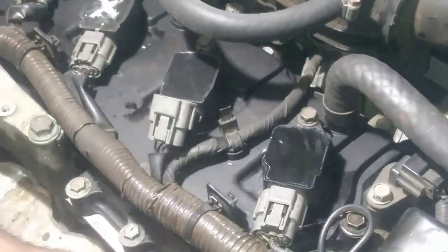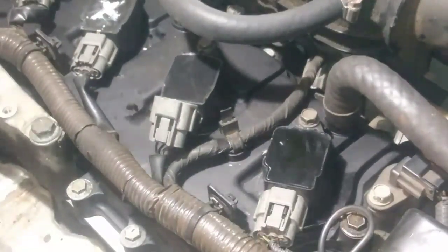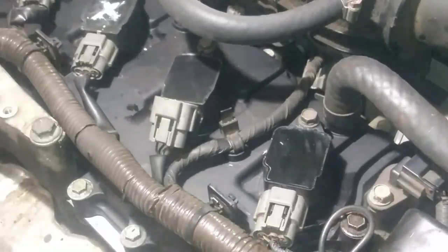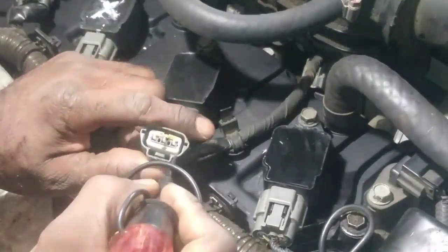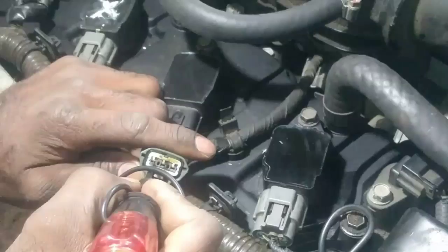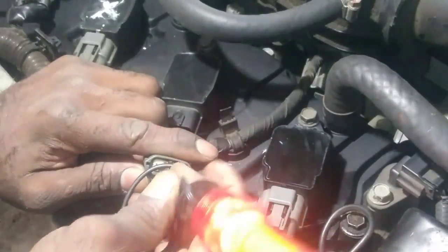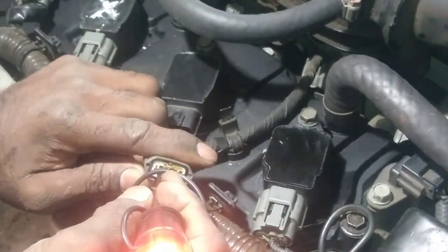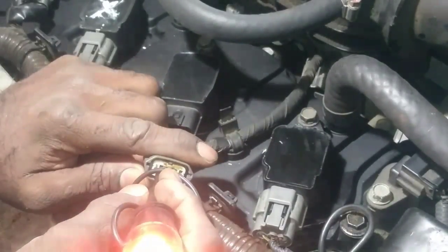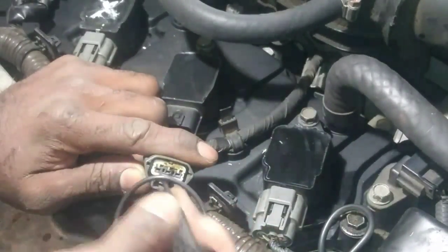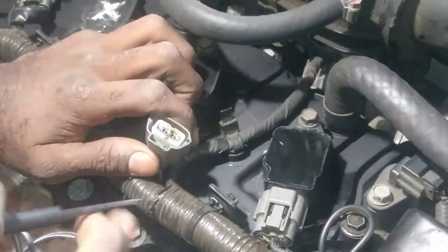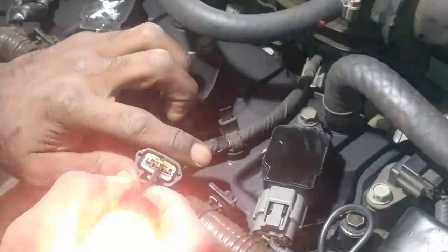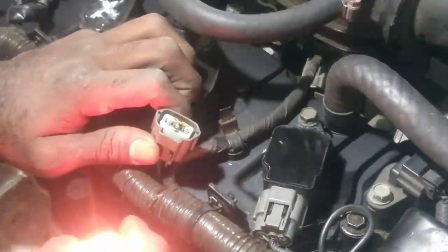We're going to check for ground, so we're going to swap this over to battery positive and check for a good ground. There's our ground here in the center. Let's check the other one. It's illuminating really faint. Again, the signaling side is going to be a low voltage reference, which is going to display that there's voltage there, but it's a resisting circuit because it's something switching inside the computer. I ain't make this stuff, but this is brighter, just like if I was to ground it here on the head, it's going to be brighter.